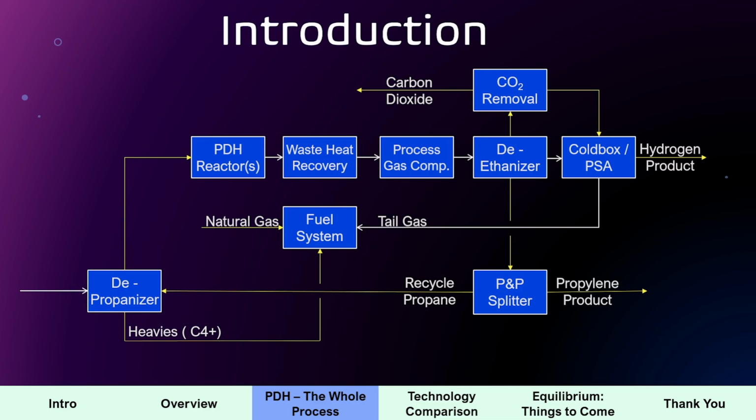So now, getting back to the undesirables. The undesirables in this case are anything like ethane, ethylene, methane, hydrogen, and CO2. What's going to happen to them? First of all, I need to separate the carbon dioxide out of the system. The reason is that carbon dioxide, as many of you would know, sublimes.